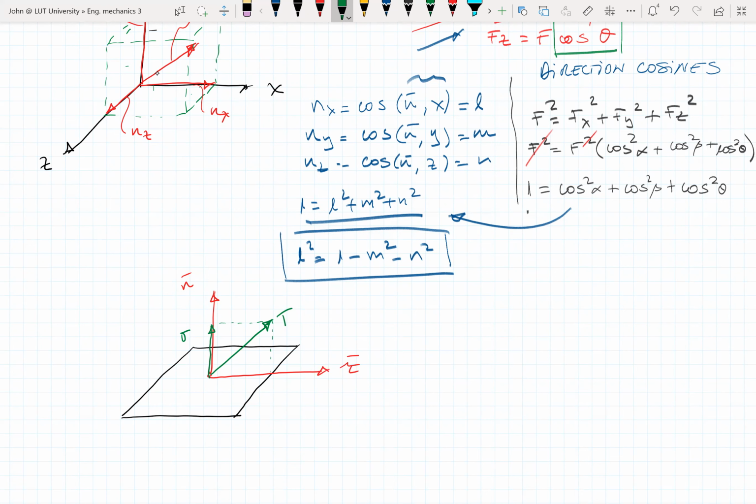And this one here I'm going to represent as tau. Meaning that if I know a vector in my Cartesian coordinate system, I could transform or orient that vector into another plane, whose main axes are going to be the normal to the plane and one shear or tangential axis to that plane.